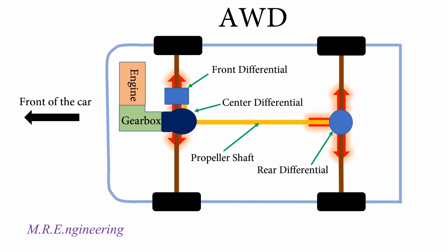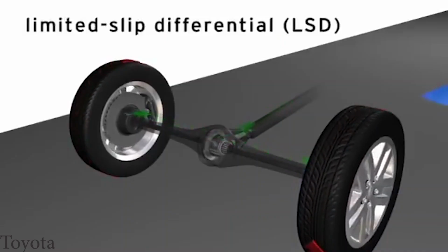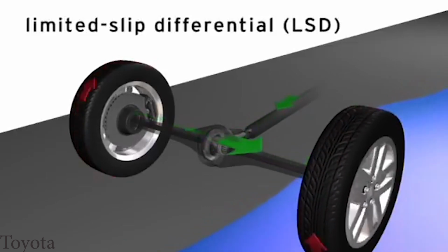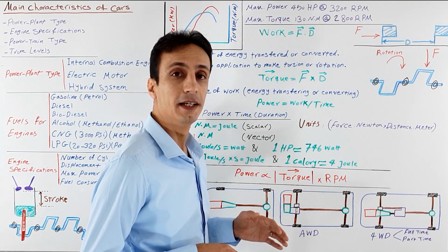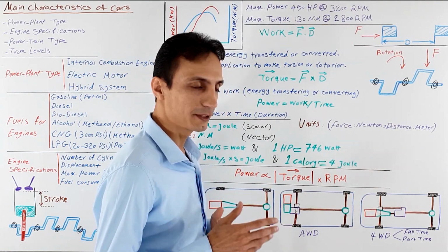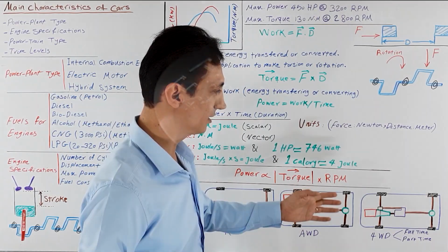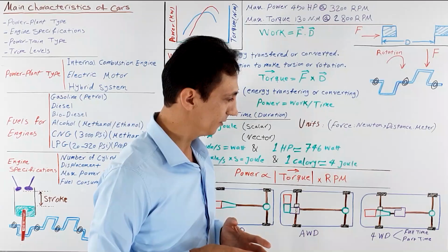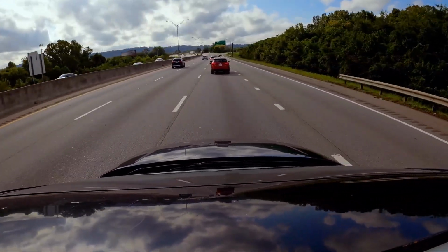But soon demand for a better and more efficient one got the engineers to make limited slip differentials. These limited slip systems make a restriction for rotation of drive wheels when or after they start to rotate without road traction and free spinning. But further development made the path for emergence of differential locks and also transfer cases that make it possible for the driver to select high and low speed driving mode. These systems are not very efficient and are suitable for off-road driving, and if you use them on pavement and highway driving, maintenance costs rise and powertrain wears more.